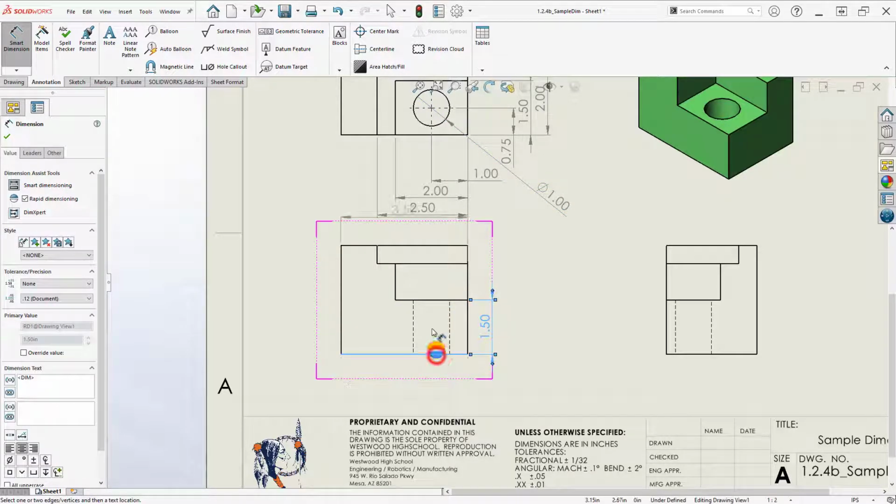My second notch height, click at the bottom, notch level, pull it out, and drop it. And I want my dimension to appear nice and neat about in the middle. Now the third one would be the overall object height, wouldn't it? And I dropped that. So now you'll notice I've got all of those object heights. So let's take a look and see if we're missing anything here.